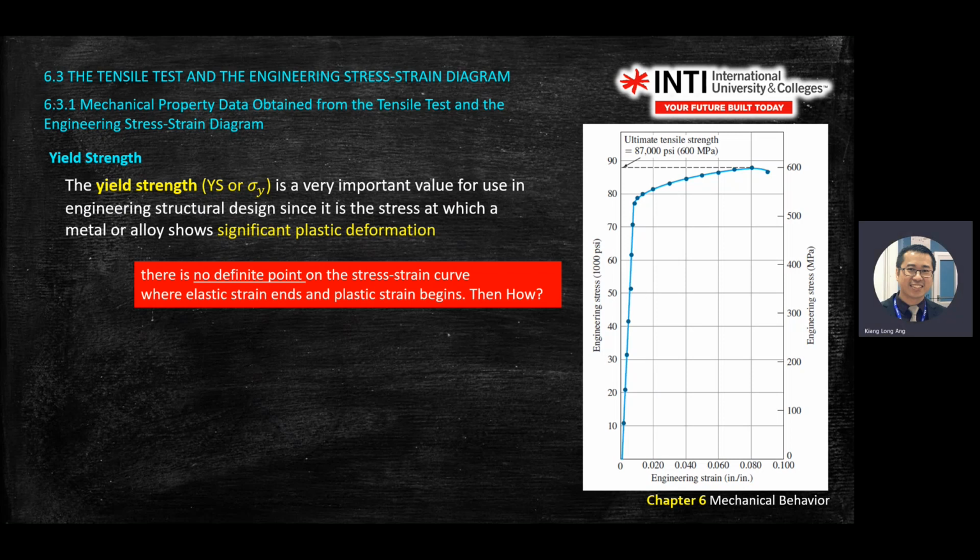0.2%. Maybe when you work in the industry later, let's say where you produce raw material, steel bar or something, your company has its own definition of yield strength, because your company has the final say on the value. When you buy material, normally they won't expose how many percent they use, but they will just give you one number.